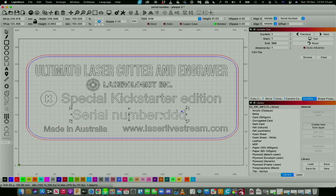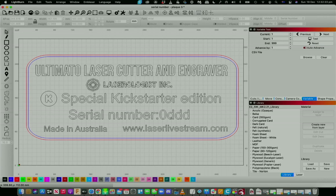So what I'm going to do here is I'm going to actually grab the text, and I'm actually going to put a 0 here. I want to show you what happens. If I test it now, you can see that it says 001. So that 0 there tells LightBurn to display all the numbers when we go through the variable text. So I think that looks a little bit more professional for me.